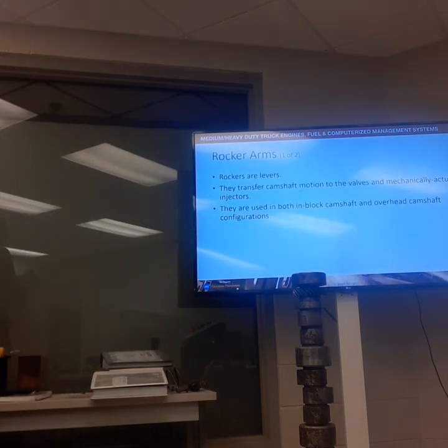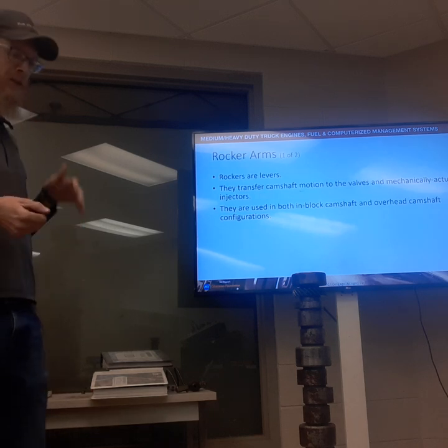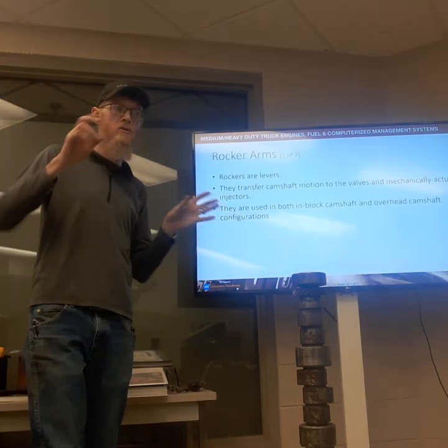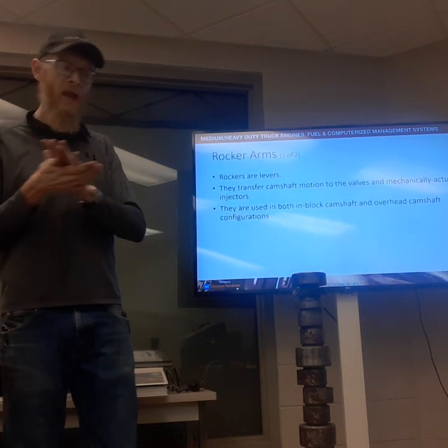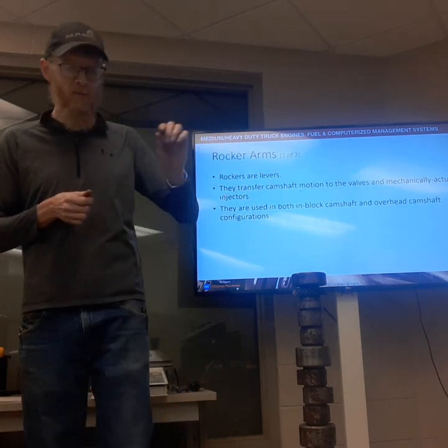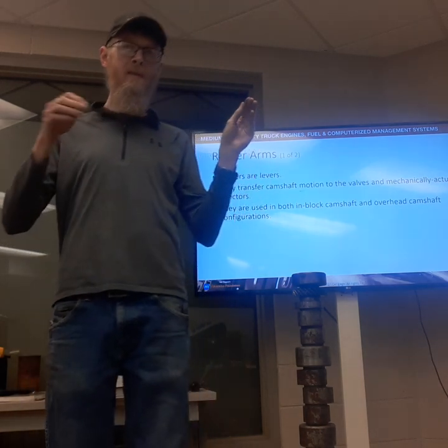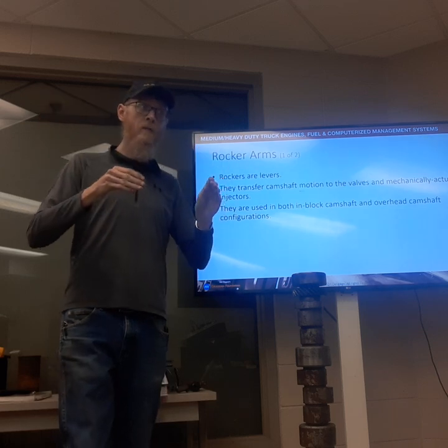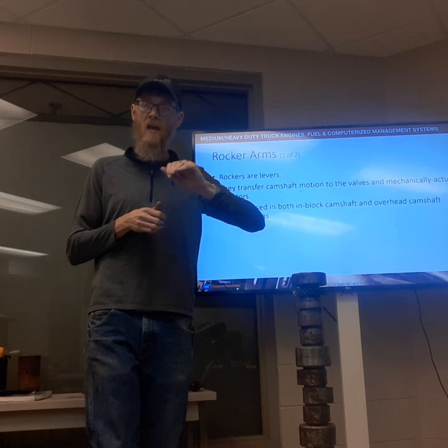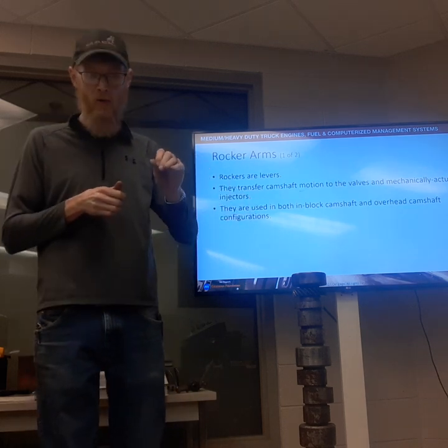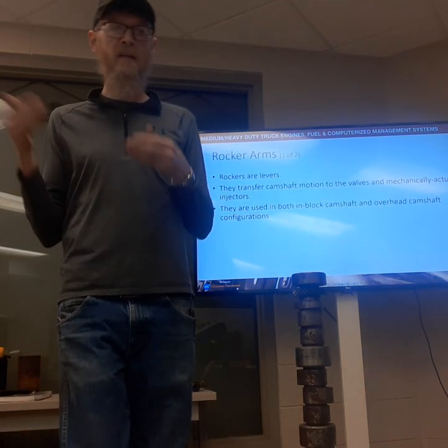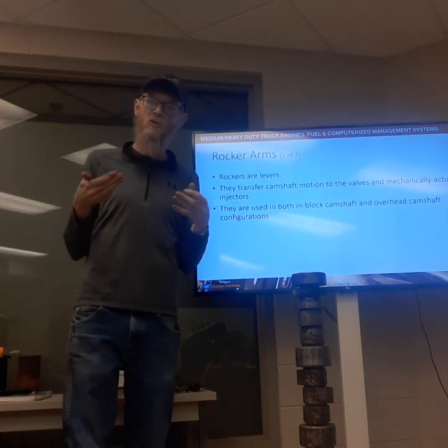You guys may also remember from our in-person lecture, we talked about that thermal expansion and drew the relationship between the heat and the amount of valve lash specification that we have, in that the exhaust valve rocker should have more lash than an intake valve rocker arm, because the exhaust rocker arms are exposed to more heat.